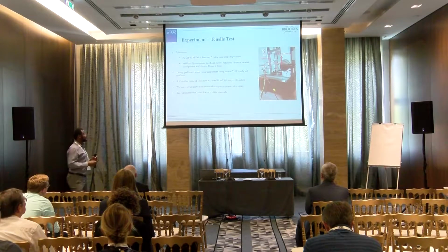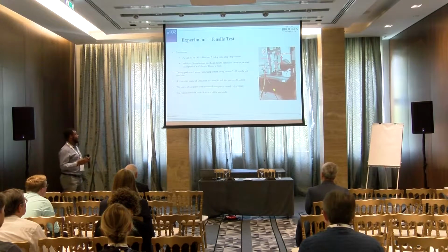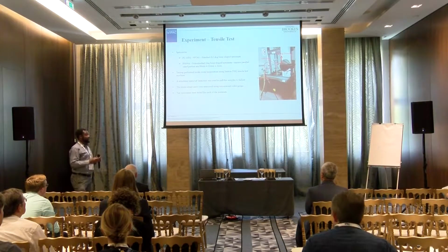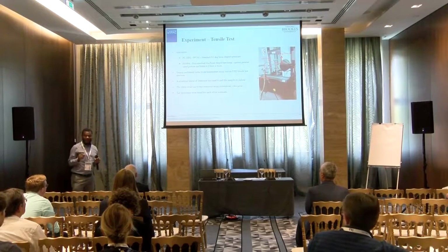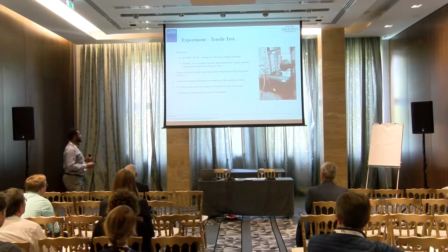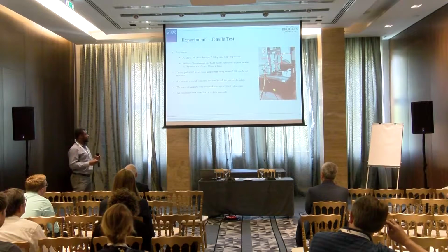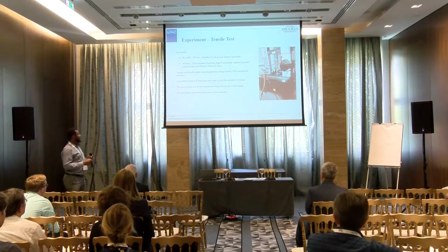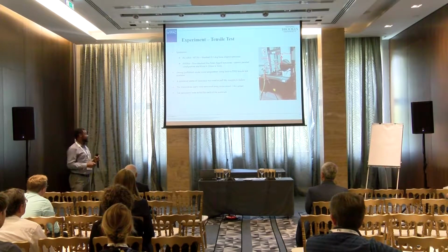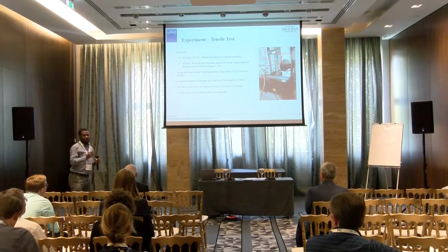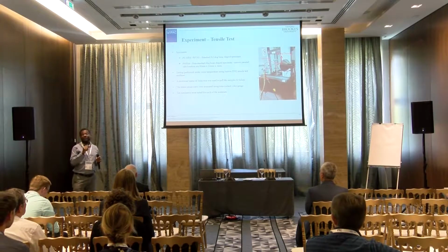So here, our experimental tensile test. PC/ABS and PP-T40 use a standard A1 dog bone specimen. For PMMA, we cut the sample out from the plaque molded at YPAC. Testing was performed at room temperature using Instron 5582. Crosshead speed, 1 millimeter. The stress-strain curve was measured using a non-contact video gauge. 10 specimens were tested for each of the materials to measure the variability, the intersample variations.